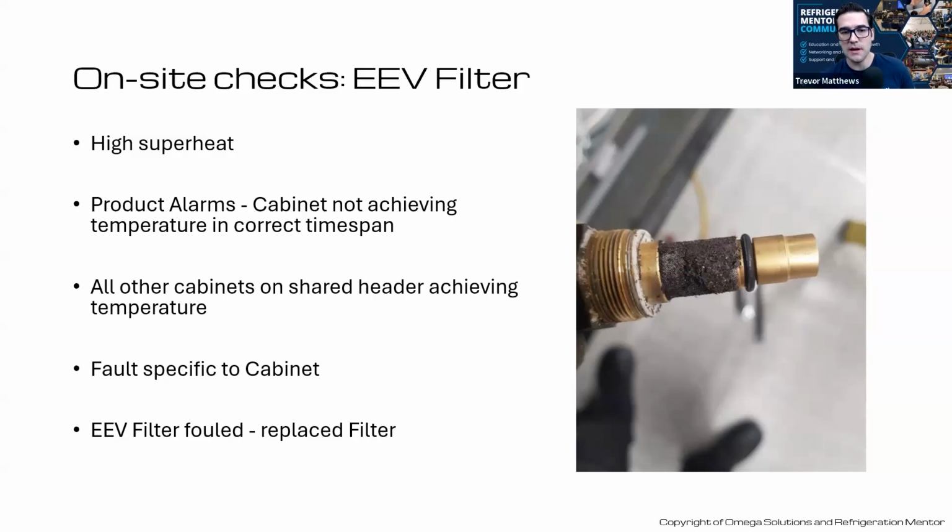And on reclaim, you can use reclaimers. The reclaimers you're using today, you can use on CO2 as long as the pressure is low enough. Think about R410A. If you use a reclaimer for 410A, low temp CO2 or subcritical CO2 is the same pressure. So just look into that with the manufacturer of that equipment, because I know lots of technicians using reclaimers for CO2 vapor and stuff like that. That's below the pressure threshold.